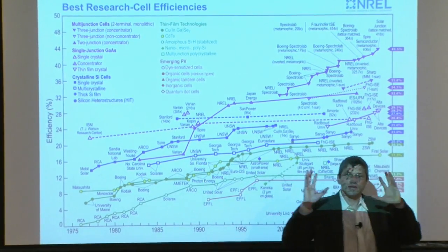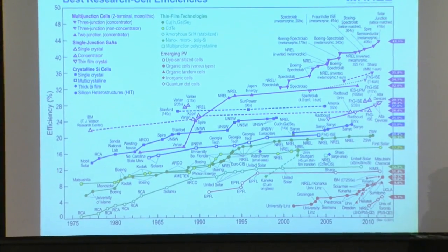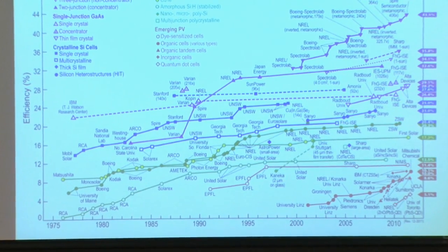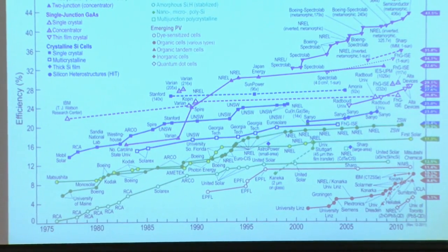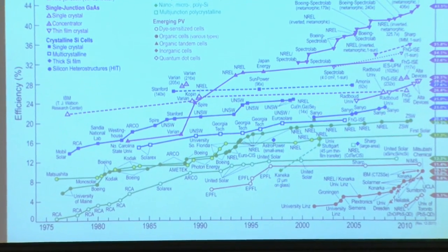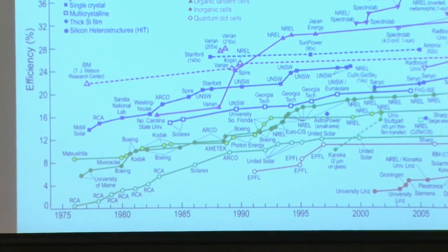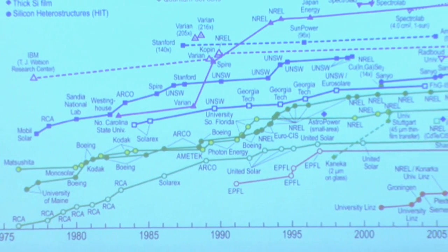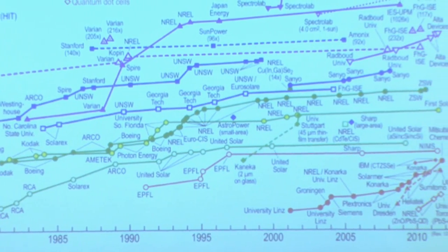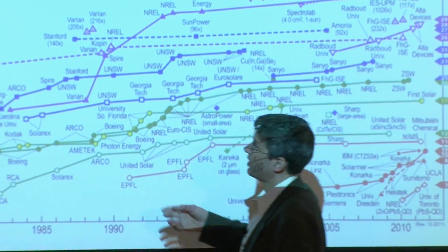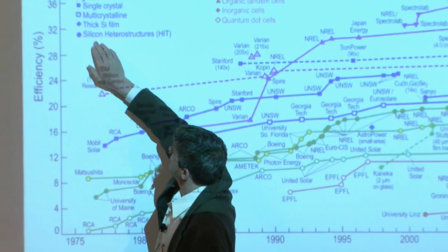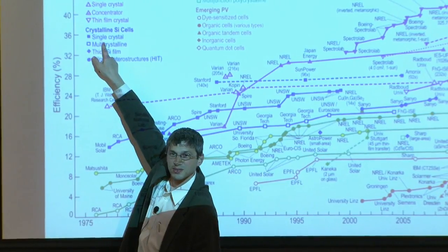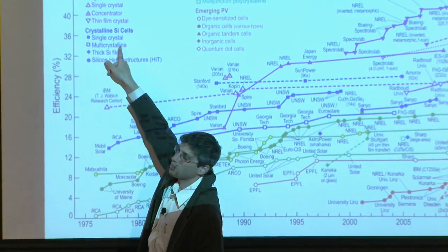So that's one of the cool things here to me. First of all, look at how many materials make electricity from the sun. Isn't that amazing? I get really excited about that. Now, when you buy a solar cell today, there's a little bit of variation, but most of the time it's made out of what? Silicon. Silicon, and in fact, look here. There are different kinds, but actually it's really multicrystalline. Single crystalline is a little more efficient, but more expensive. So most of the cells you buy are multicrystalline.